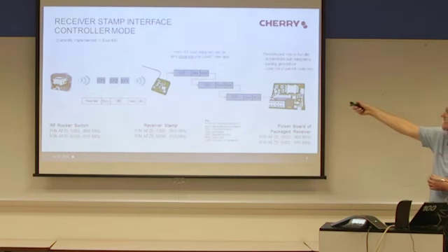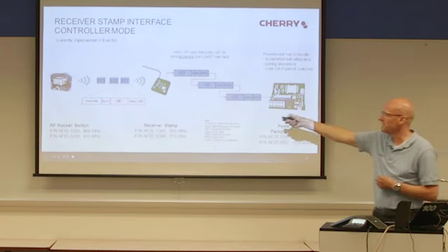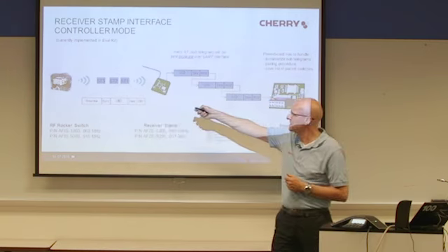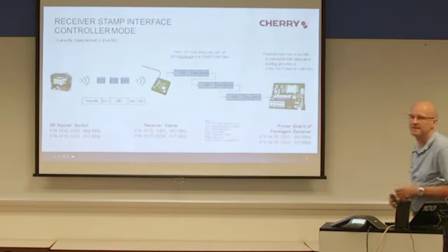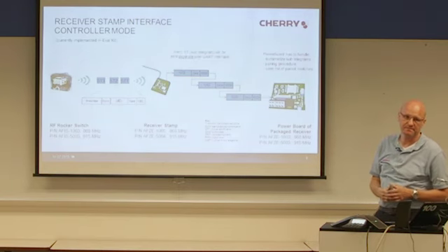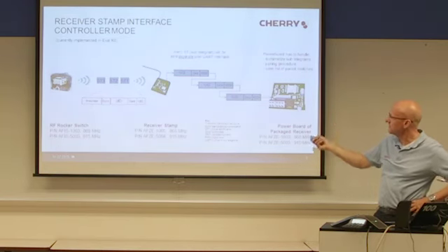And the power board has saved the list of the paired switches, because the RF stamp is stupid. The RF stamp only gives 3 subtelegrams through to the power board. So the power board has to save the paired sender list here. This is the current state.